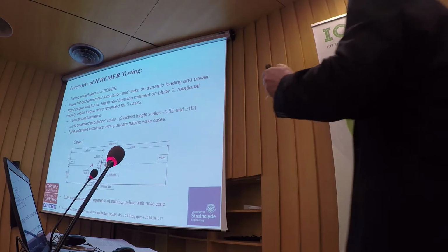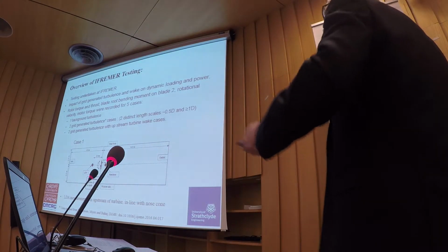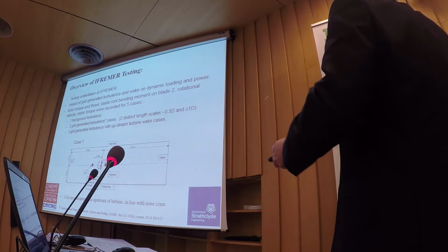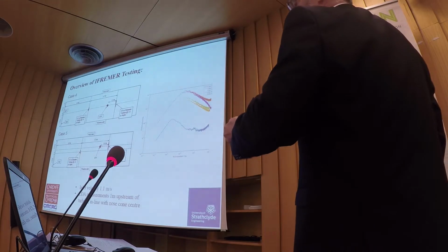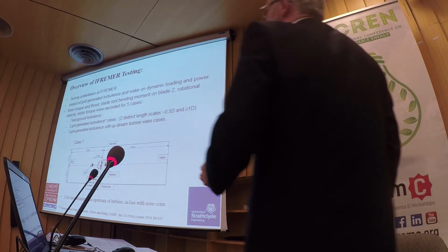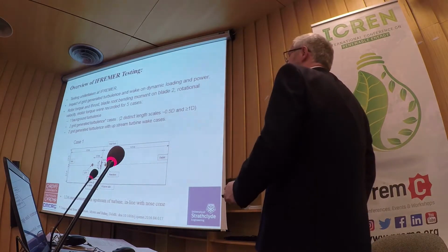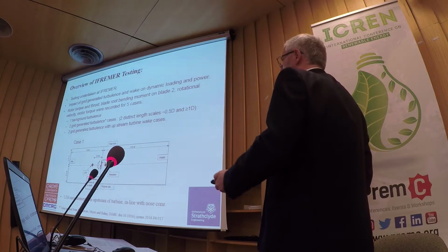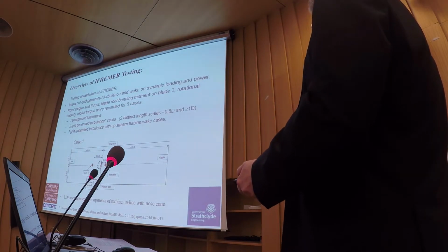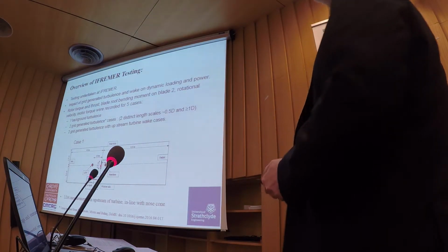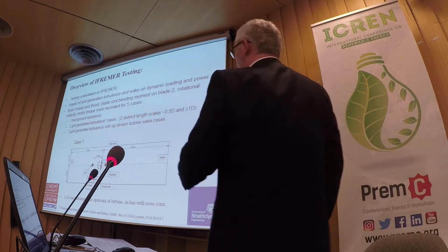So just quickly through this, we've got a number of cases that we've done some testing on, and we've used the work that Blackmore et al. did in Southampton. We've created some turbulence by putting different size grids upstream. So the first case, there's no grid, so the turbulence is, I don't know, 1.75, I think it was. So we have an inlet of 1.1 meter per second, but we measure a meter upstream of the turbine in order to get a decent value of what's actually hitting the turbine.